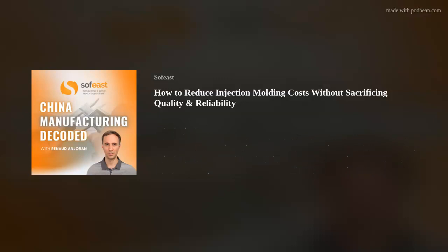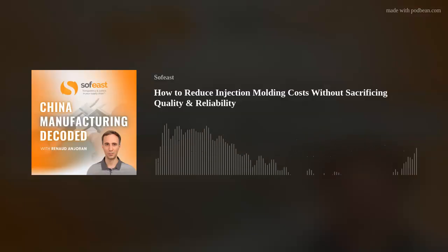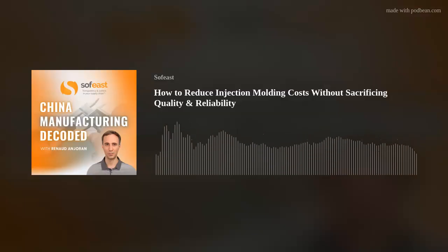Another big one is draft angles. Throw your mind back to when you were a kid, building sandcastles on the beach. You had one of these little castle buckets, and it was almost like a pyramid. You threw your wet sand in, you turned it upside down, gave it a bang with your spade on the top, and everything came out perfect. Why? Because it was a pyramid. In other words, the draft angles were so big that as soon as you came away half a millimeter or a millimeter, the bucket was no longer touching the sand and everything was free. That's what you call your draft angle.